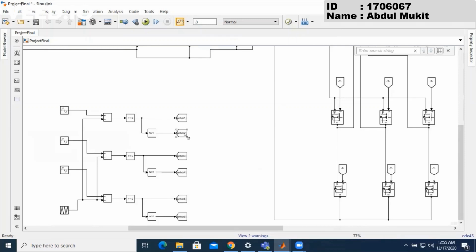Now we use an inverter to convert 300 volt DC to AC. The inverter uses the pulse width modulation method to convert DC to AC. Here, the MOSFET is an important element. We implement pulse width modulation by controlling the gate voltage of the MOSFET to keep it on or off a certain portion of the cycle. We need 2 MOSFETs to create a single phase. Here, 6 MOSFETs are used to create 3-phase voltage. Now, the number of times the MOSFET turns on or off is called switching frequency. Here, the switching frequency is 6750 Hz.